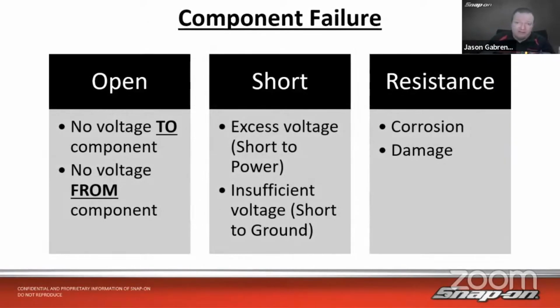Now, when we're testing a part, we have to take into consideration different modes of component failure. If I'm going to think about how a component can fail and how I'm going to test it, it really falls into these 3 buckets. We're going to have an open, a short, or a resistance issue.